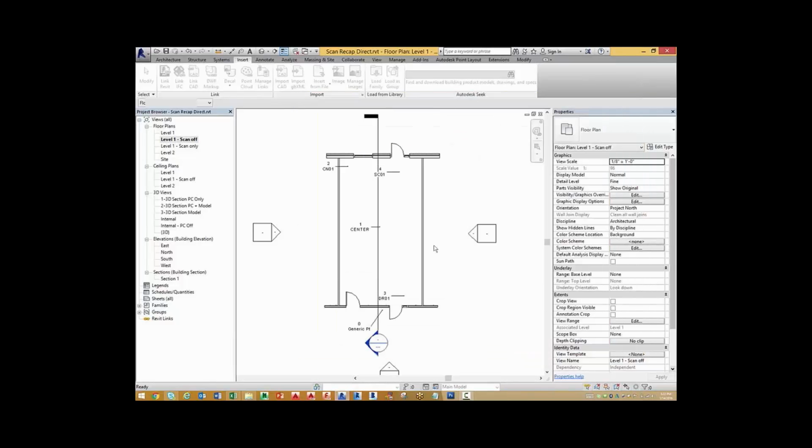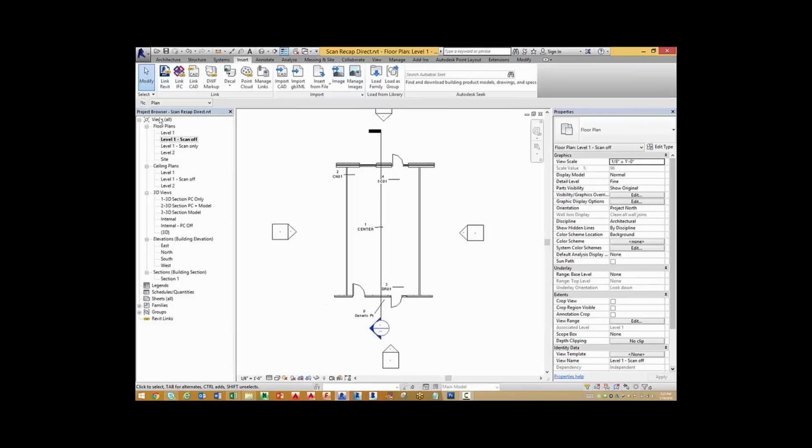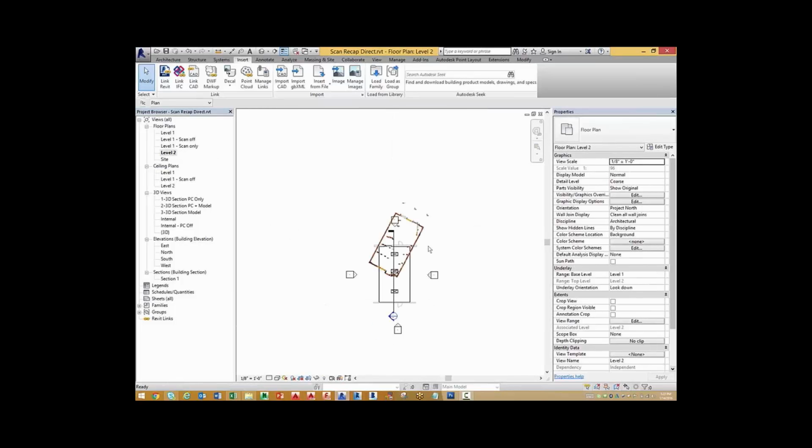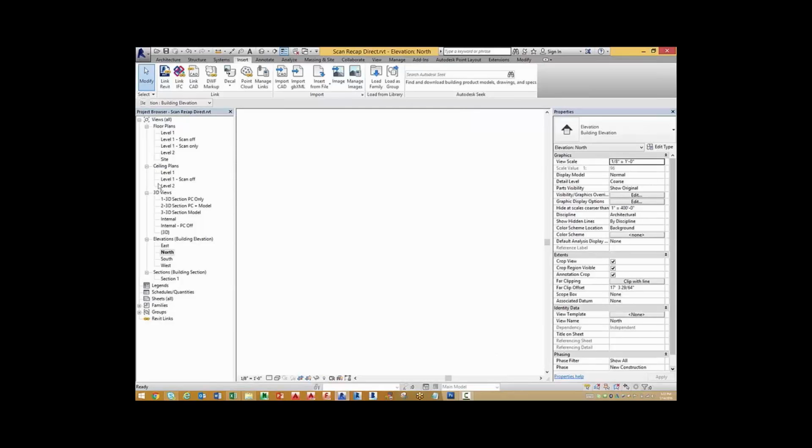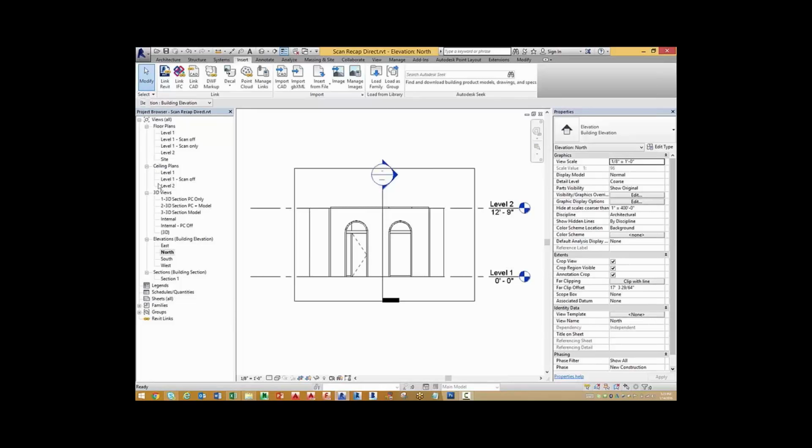Well, CAD models, Revit models, they all have an origin. Well, so do the scans. They all have an origin. But when I bring this in, I'm like, where's my scan? Well, it turns out it was actually on a different level, and it was still rotated, but it was much higher. So origin to origin didn't help. But again, what do most people do? They'll rotate it, and they'll move it down to get it lined up with where they want it to be, but it's not as accurate.